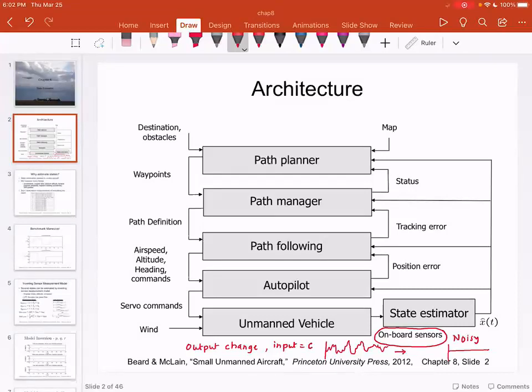Now that creates a problem, because depending upon how the output varies, it could be a deterministic variation, which means you can program it. For example, if you have a weighing scale and every time the weighing scale is offset by 10 pounds, you can subtract those 10 pounds and still get accurate measurement.